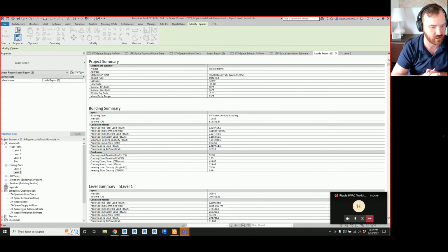The out-of-the-box Revit HVAC zones are not helpful. They never defined if they're supposed to be VAV or air handling unit, and they have elements of both in there, so it just made them not helpful. So when you're using the toolkit, disregard the HVAC zones. When the VAV and air handler zoning program comes out, that will have new parameters that allow you to zone based on that parameter. That's something that's in the works that'll be out after the diffuser layout tool.